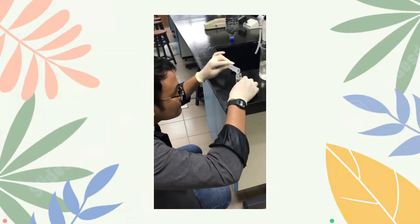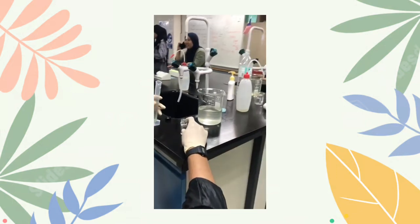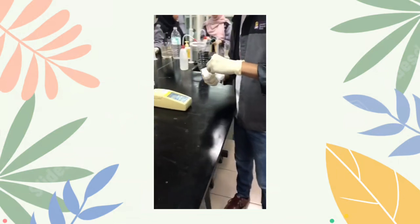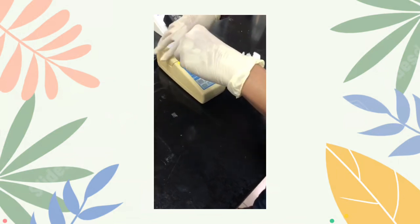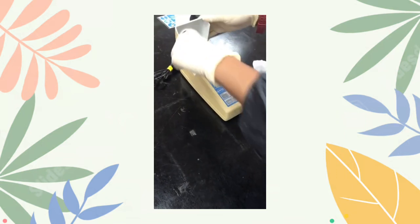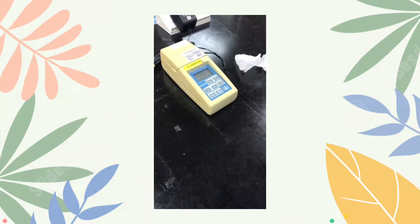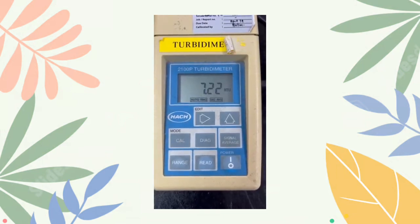Pour the water that has been purified into the turbidity bottle. Clean the turbidity bottle containing the unpurified water sample and put it in the turbidity meter to get the turbidity reading. The result is 7.22 NTU.